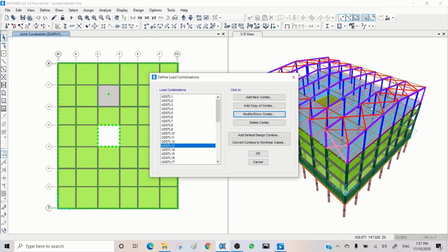If you use automatic wind and earthquake load calculations and you can manage everything properly, then that's perfectly fine. If it's a simple building, for example with simple dead and earthquake load, something like a warehouse that you are designing, and you have simple combinations, you may use standard load combinations.